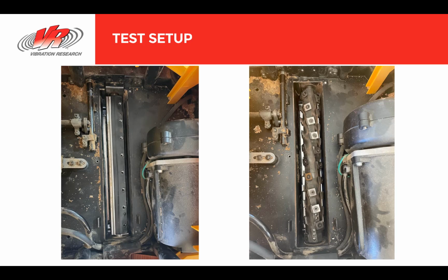This has a significant difference in that the blades don't meet perfectly perpendicular to the wood, so they have more of a shearing motion, as well as the number of blades that are constantly in contact with the wood. With the 3-blade configuration, you can see that every time one blade passes, there is a small gap before the next blade, and this can create noise. With the Helix head, there is always blade or blades in contact with the wood as soon as it starts. And that led to some interesting results that we will see.